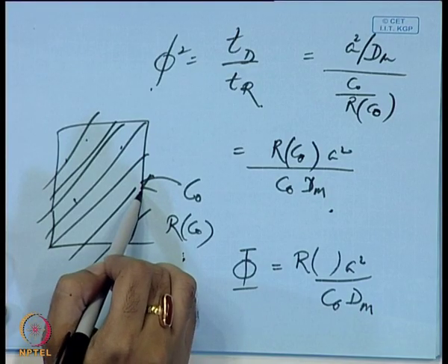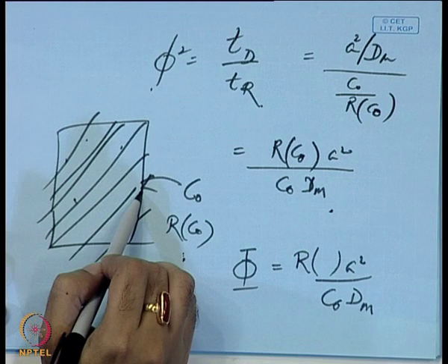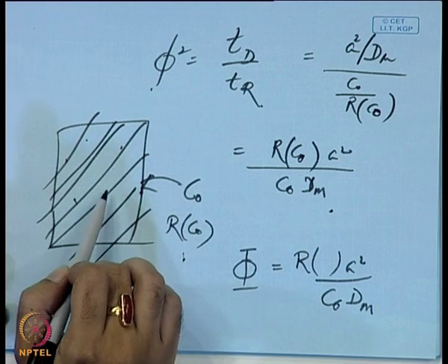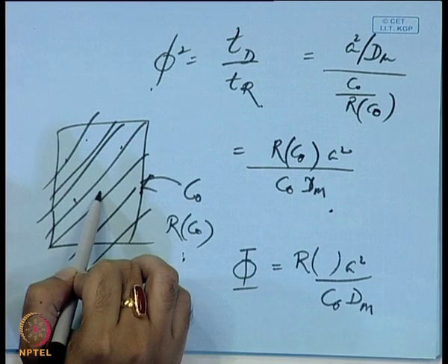See, let us understand two things, that the surface reaction rate is not a true representation. That is the maximum reaction rate possible, because the concentration is maximum there, and concentration inside the matrix varies from point to point because of mass transfer limitations. Now, which point? This is a very straightforward answer and you should come up with it, unless you are really groggy. At which point should this concentration be measured?